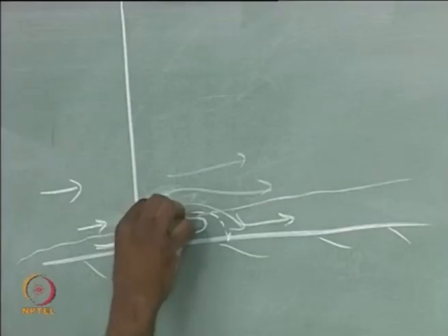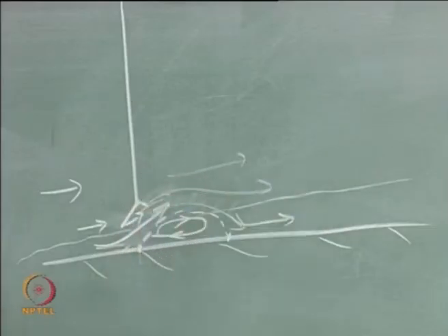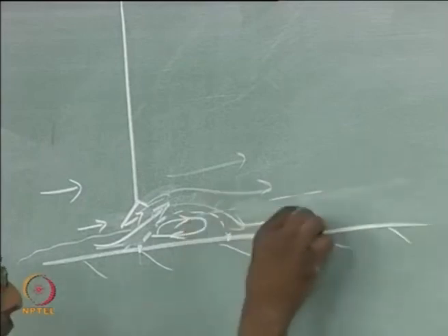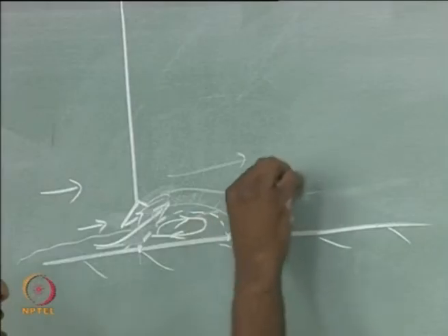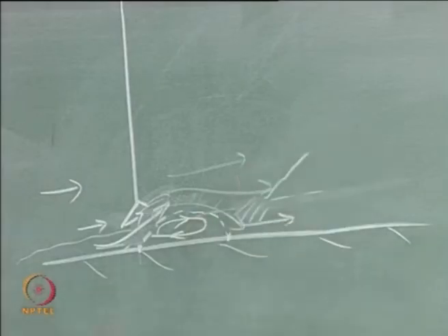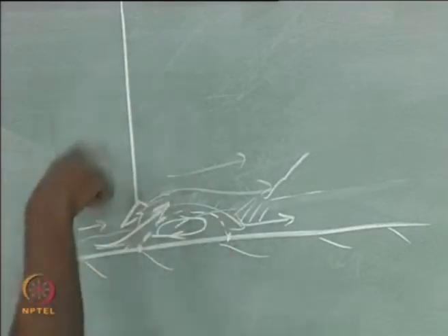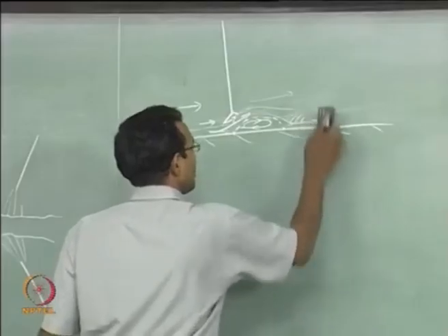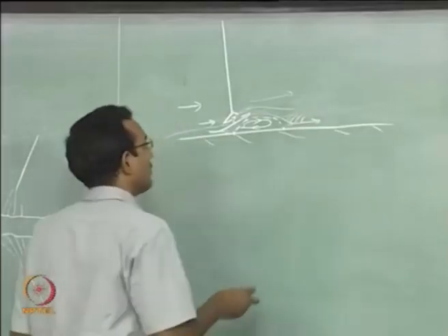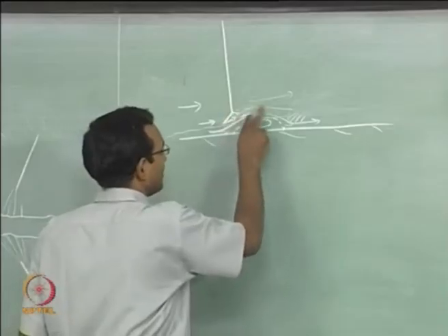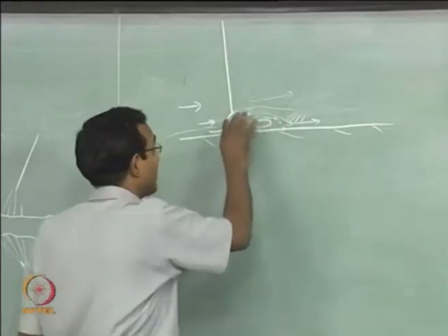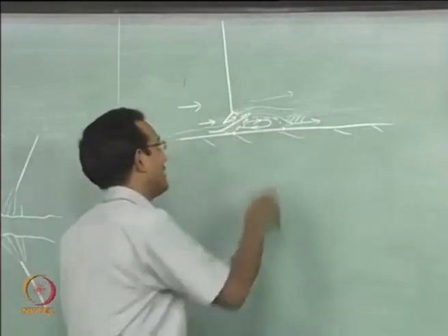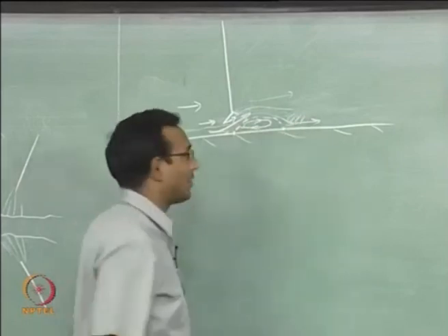If it is supersonic flow, then there will be expansions. If there is expansion, and then again the flow has to turn back, there will be compression waves which will again form a shock. This is the case not for a normal shock problem, but an oblique shock problem. For a normal shock problem, there will be no shocks formed downstream. But if it is a transonic zone, if the Mach number is close to 1, then you will still see the expansions and compressions if you look at some particular density map. You will see that the density decreases and increases again. All that you will see.